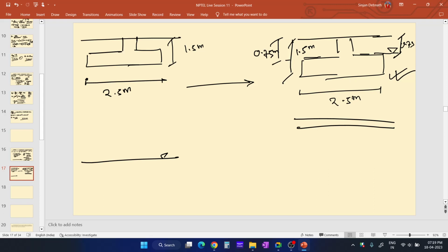Let us use the equation for ultimate bearing capacity. So for the second case, we need to determine the effective overburden pressure at the base of the foundation. So how much is it? It is 0.75 above the groundwater table, 0.75 into gamma, plus this part, which is 1.5 minus 0.75, also 0.75. So that means 0.75 into gamma plus 0.75 into gamma submerged.